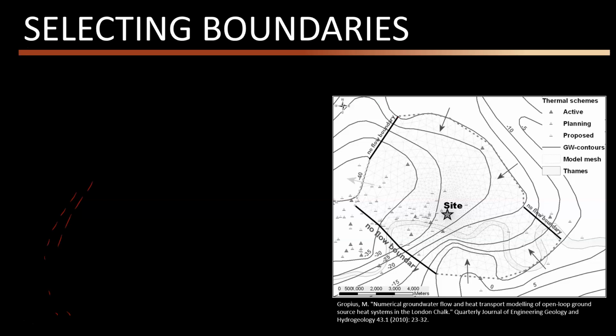But there is one important thing that you need to be careful with. That is the fact that these no flow boundary conditions that we have found can move. What does it mean? If you find a potentiometric map like this, you will see that there's a date on the map.